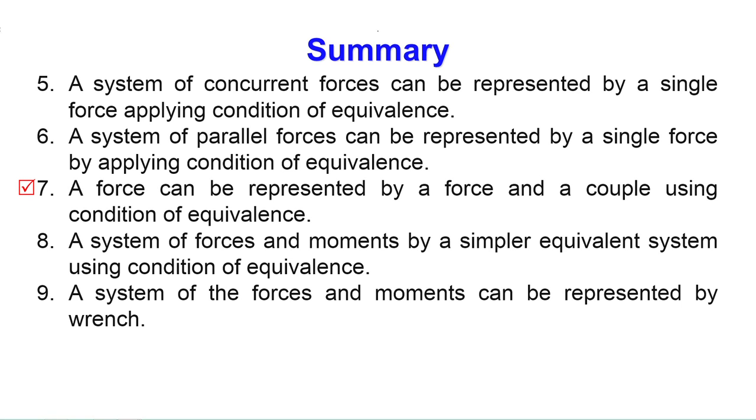Then we have also shown that a force can be represented by a force and a couple using the condition of equivalence. A system of forces and moments can be represented by a simpler equivalent system using the condition of equivalence. And lastly, a system of forces and moments can be represented by a wrench.